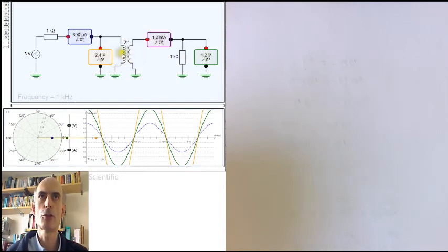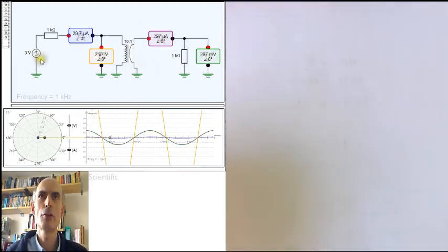The voltage has gone down by a factor of 2 because the turns ratio is 2-to-1, but to preserve the power, that means the current has had to increase by a factor of 2. If I increase the turns ratio to, for example, 10-to-1, then there's a very small amount of load being taken from the primary.